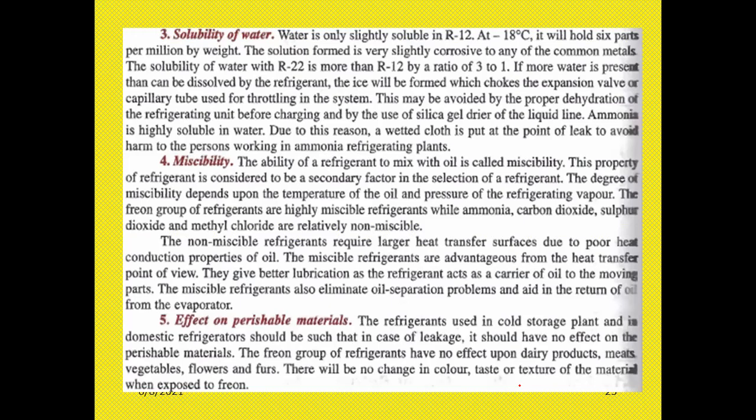This may be avoided by proper dehydration of the refrigerating unit before charging, and by the use of silica gel for drying the liquid line. If water is present and not dissolved in the refrigerant, ice will be formed at the choke of the expansion valve.